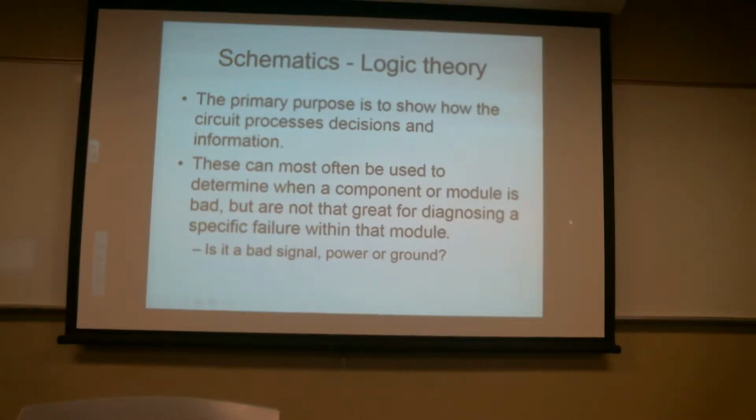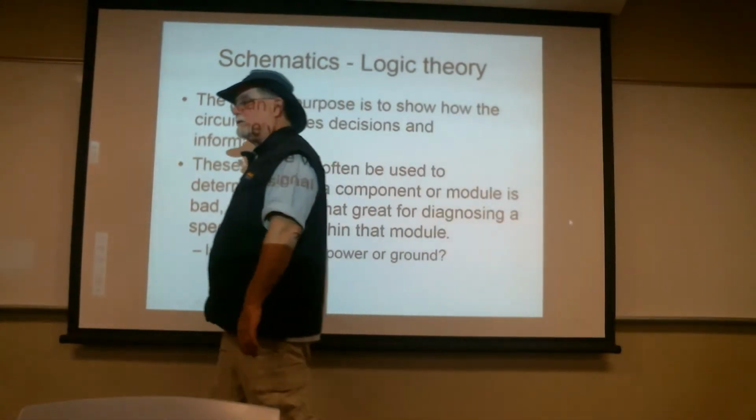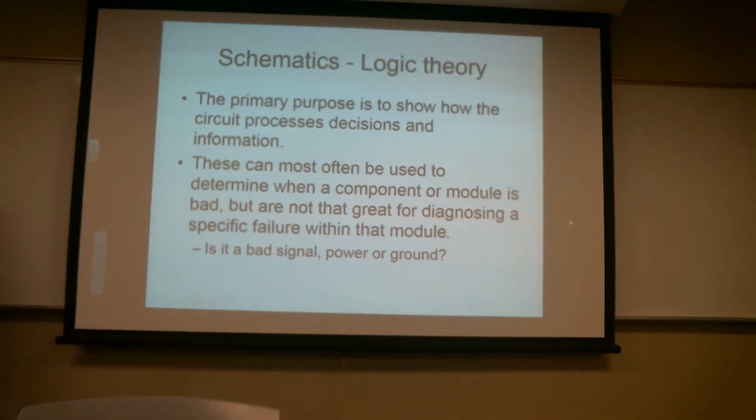However, having some knowledge about how this works allows you to identify: is it the computer? Is it the output transistor? Is it the load? Is it the wires in between? Is it the power source? All of those components very likely can be bought. Is it one of the sensors not providing appropriate data?